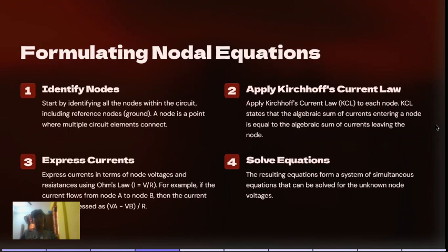Formulating nodal equations. Identify nodes. Start by identifying all the nodes within the circuit, including the reference node, ground. A node is a point where multiple circuit elements connect. Apply Kirchhoff's current law. Apply Kirchhoff's current law (KCL) to each node. KCL states that the algebraic sum of currents entering a node is equal to the algebraic sum of currents leaving